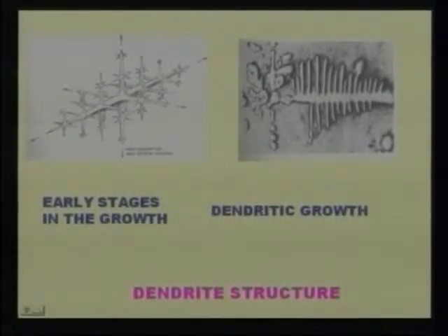Now you can see a real metallic picture of the iron carbon material. You can see this is the backbone of the dendrite growth. First it will form this backbone, then these are slowly absorbed by cooling. When cooling continuously takes place, slowly these stems are absorbing the smaller crystals, and the entire liquid metal solidifies, and you will have a growth. This type of growth is called dendritic growth.